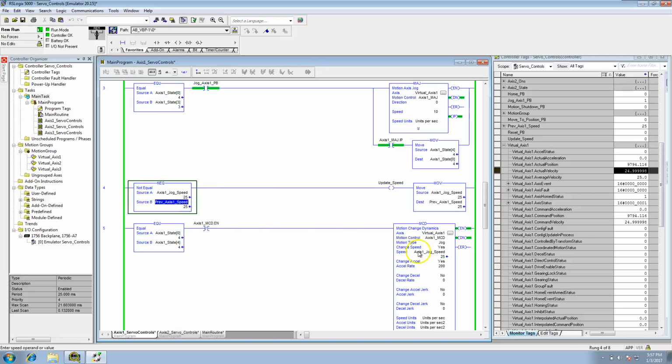Now, what's updating first is always going to be the motion. However, we're using more of our processor at that point. So it's not best that you use the command like that. As far as using the enable, yes, it will work, but you will utilize more of the processor's ability and kind of just bog it down.